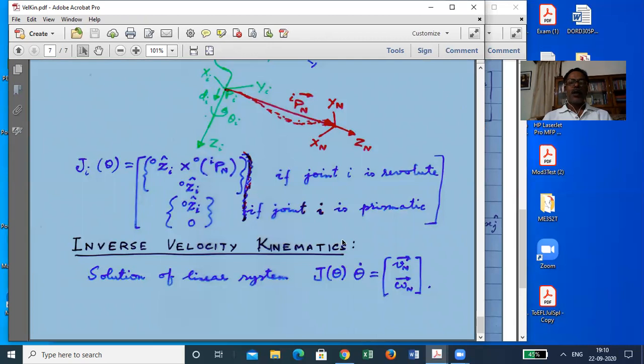And once we have got this, then with the given input velocities, the output velocities, that is the hand velocities, you can directly get from here. But make note, this gives you directly the output hand velocity only, not intermediate points, not intermediate frames.